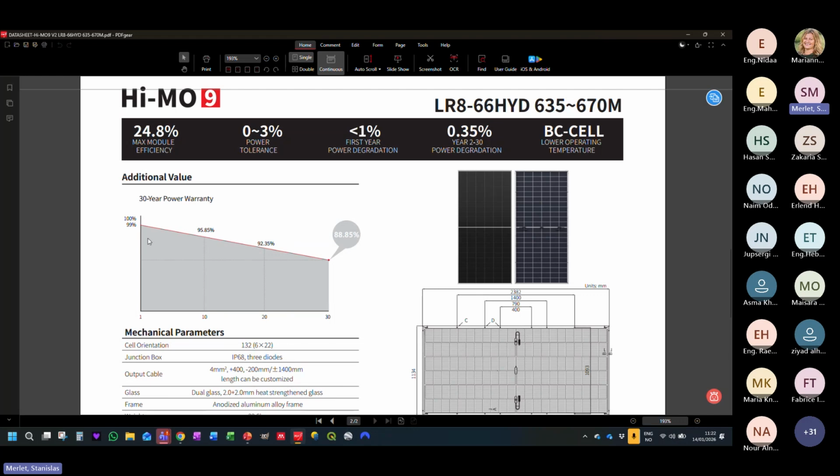According to technology, you might have a loss at the very beginning, the very first hours of exposure to sun, and it's usually no more than 2%. So they say that in year 1, you have 1% loss. So you go directly from 100% to 99% of efficiency of the module. And then in time, they will warranty a degradation rate.